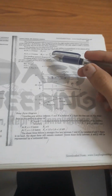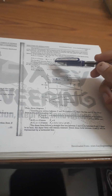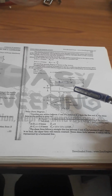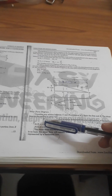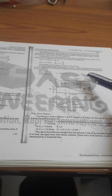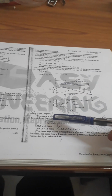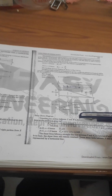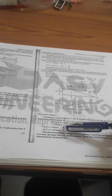A cantilever beam of length 2 meters carries a uniformly distributed load of 1 kilonewton per meter run over a length of 1.5 meters from the free end. If we consider a section between C and B, then Fx is equal to plus W into X, which is equal to 1 into X. At B, X is equal to 0, hence Fx is equal to 0.